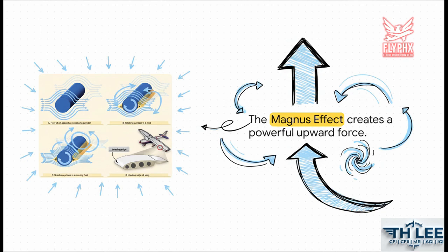The sharp trailing edge of the wing actually forces the rear stagnation point, which is where the airflow separates, to sit just aft of the wing. This effectively pulls that low pressure into a really powerful upward force. It's just fluid dynamics at its absolute finest.